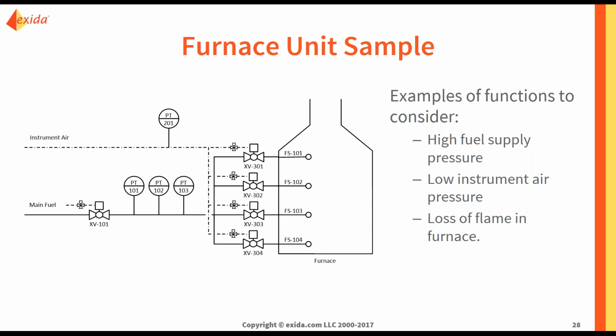In that case, you might have too much fuel in the furnace, which could cause an explosion in that furnace. So we have a SIF to protect against that. What if you have low instrument air pressure in the instrument air line? In this case, you're not controlling your valves optimally, and therefore you could have a little bit too much fuel or a little bit too little fuel in the furnace. Again, this could cause a potential hazard, such as a furnace explosion.